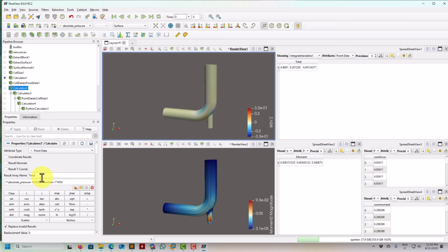The first one is to compute the total, which is a summation. Remember that now in Fluent it will be absolute pressure minus this one to get the relative normals, and wall shear stresses, the vector I just assembled. So here I'm just getting the total of these two fields, which have units of Pascal, so they are not the force. Then calculator 3, I compute the moment, so it's the cross of total and the reference vector 0, 0, 0, I hat, J hat, K hat. We saw with wall shear stresses that you are basically assembling a vector, and you get the coordinates here.